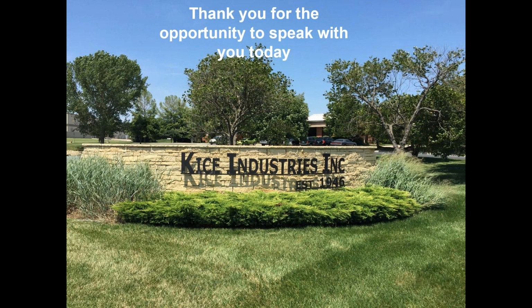So if we can take a step back and say, I change my filter bags once a year now, what happens if I change my process and clean the bags offline during shutdown? I wouldn't have any doubt that you may increase that 12-month filter bag to 15 or 18 months just by using that added cleaning cycle. Again, it depends on a lot of different things, but you will see a life increase on those filter bags by cleaning offline.